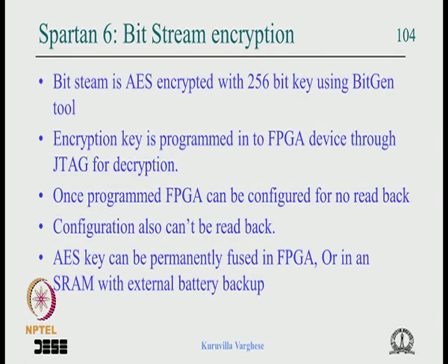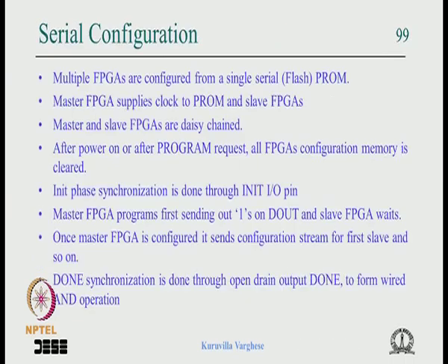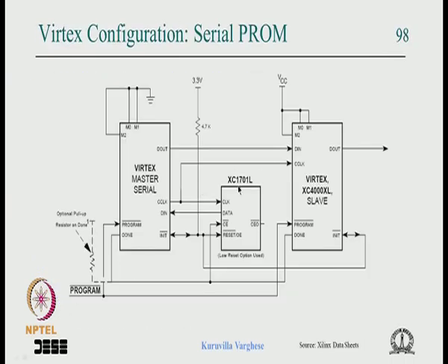And another issue with the earlier FPGAs was, suppose you come out with a proprietary design, you put the configuration bit stream in this PROM. Okay, now you send that into the field on a PCB or in a product. What can happen is that at power on somebody can capture this data, because it's very easy, because the clock is coming in synchronous, the data is coming. So this can be easily reverse engineered. Somebody can read the bit stream and reverse engineer the complete system.